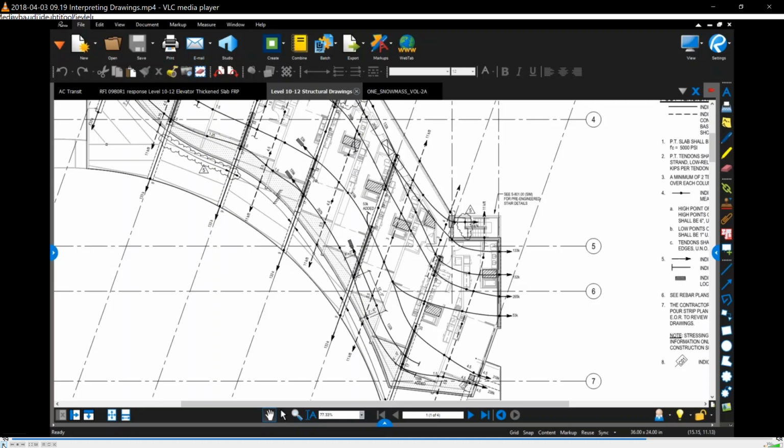Yes, sir. How can they stress the tendon in the middle of the span? You provide an opening. So the tendon comes out at the midpoint of that, and then you put in what's called a stressing ram. You put that inside the hole, and you pull it. Yeah, you pull the tendon through. And that's all you're doing.